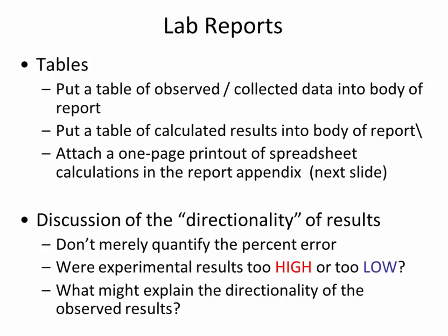So that means on average, the experimentally observed discharge coefficient was lower than what it should have been when we predict it based on the theory that governs how you would develop a C sub D. In italics beneath those two figures, I made a little note to myself, so that I'd remind myself to write it in the lab report: on average, the experimental C sub D is less than the C sub D should be based on theory.